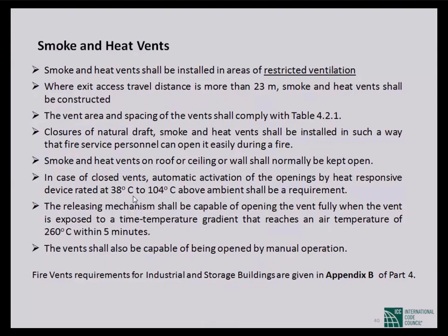That is the restricted ventilated area. You have to remove the smoke from that area. So you need some vent so that smoke will be released out, so it will not accumulate inside the building. So in case of fire, there will be no accumulation of smoke and the people can evacuate very easily.